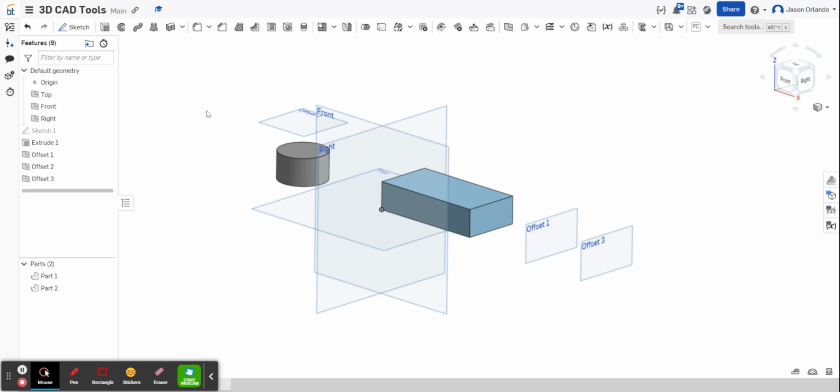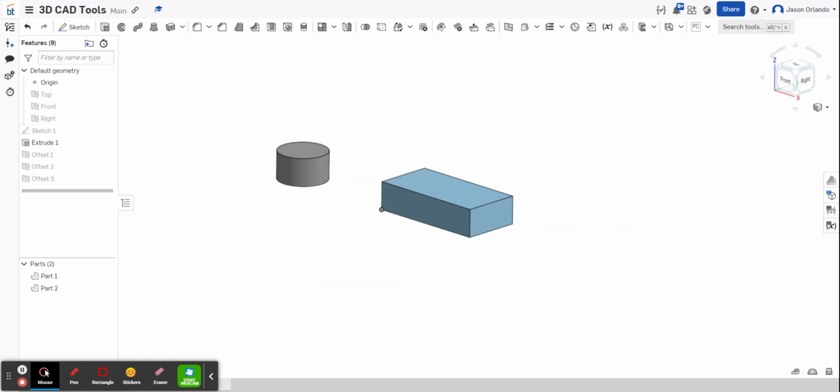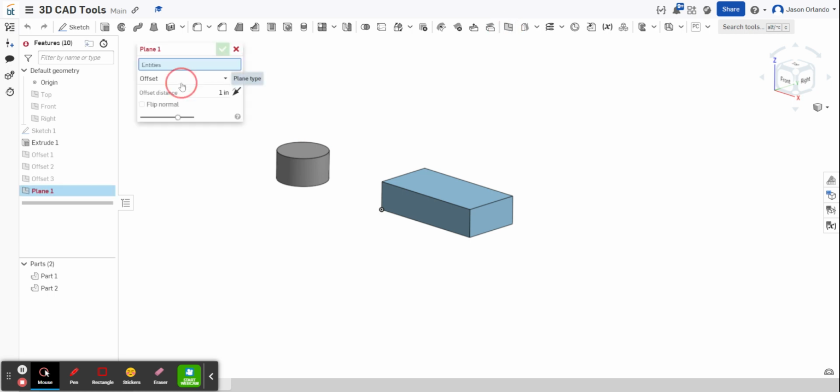All right, now we may not want to keep all of these visible. So remember that we can show or hide all planes together with the P button on our keyboard. P as in plane, or one at a time. We can click the little eyeball to show or hide the visibility of each one. So if you think your document's getting kind of crazy and you would like to hide those, you can do that. All right, the next plane tool is the plane and point.